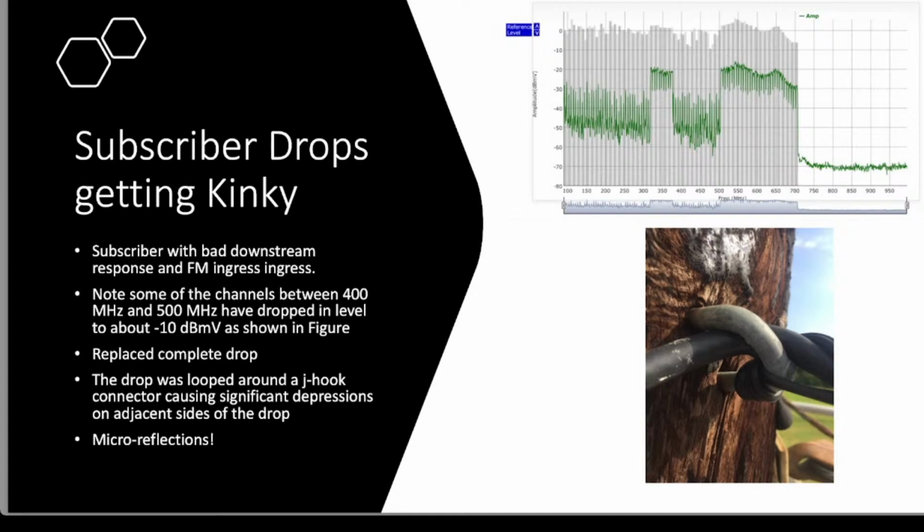a J-hook into the telephone pole, which was basically what was connecting the drop or holding the drop up in the air, going down to the subscriber's home, and the coax cable itself was wrapped so tightly around the J-hook that it had created a kink in the coax cable. We've talked before about how we don't like to use staples on coax cables or anything that's going to create too much of a bend in the coax cable. That creates a kink.